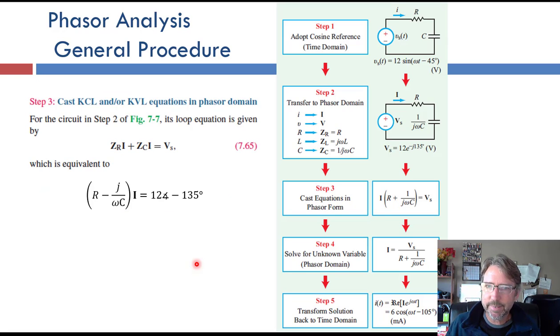Okay, so then the next step is to do our circuit analysis in terms of impedances. So we have a resistor and we have a capacitor, and we treat them the same. That's the great thing. No differential equations. They're just things with impedance. Often we'll redraw the circuit with just boxes there. Going around this loop, the voltage across the resistor plus the voltage across the capacitor has to equal the voltage across the source. So that's Kirchhoff's voltage law.